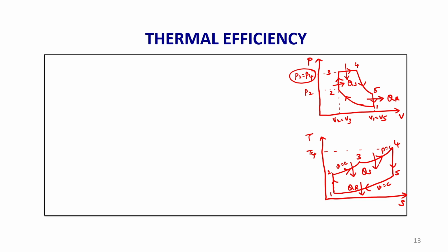Okay. So, now let us define the air standard efficiency or thermal efficiency. Output by input, W net by heat supplied, that is QS. W net is heat supplied minus heat rejected divided by heat supplied. So, divide the numerator and denominator. QS by QS is 1 minus QR divided by QS. So, this becomes equation number 1.